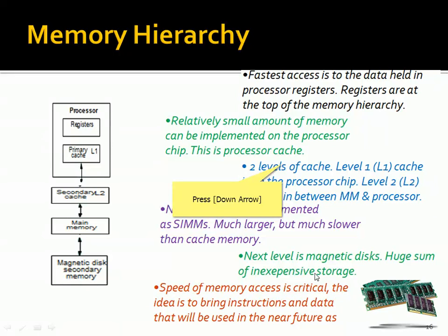For specific applications such as the airbag in a car, a weighing machine, a microwave oven, right? Those have specific applications. In that case, a microcontroller will be used. A microcontroller always puts the instructions and data in a single memory and handles them, because only a small amount of data and instructions will be there, and they will be repeatedly performed. So they will be stored in a memory. So the speed of memory access is a critical aspect for some applications.